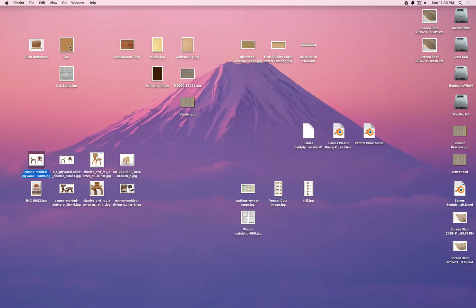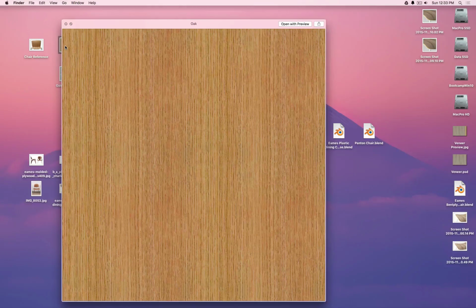So how does the bump mapping actually work? We can have a texture like this, and this is basically what we have to use as a bump map. So it's kind of a black and white image. The white, let's say, goes up and the black goes down, if you want to think about it this way. So that's the reason why we have to work with pure white and pure black, and then the grayscale steps in between. That will then define the bump mapping.